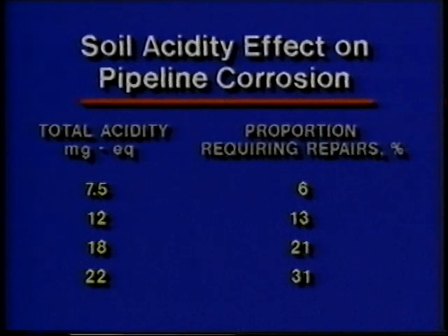A soil with a pH of less than 4.5 would be referred to as extremely acidic. From pH 6 to 7 to 8, we would refer to it as being a neutral soil, and a soil measurement on the order of 9 or 10 would be referred to as an extremely alkaline soil. So the pH of soils ranges from about 4 to 10, with the bulk of the soils having essentially neutral type conditions.